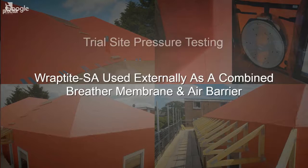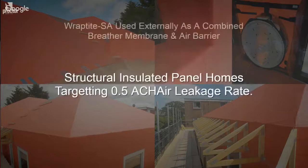So what the Wraptite-SA does is combine very high vapour permeability with low air permeability. And because it's actually self-adhesive, it allows for a quick and simple installation process on or off-site. So although this building looks quite traditional in its outward appearance, it actually uses very high-tech structural insulated panels, otherwise known as SIPs. The performance of these panels, along with the 0.5 air changes per hour air leakage rate, provides a very highly efficient envelope, which in turn then delivers very low running costs over the life cycle of the building.